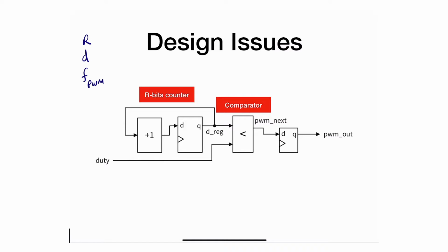So we need to improve this design a little bit so that we can control the frequency of the pulse width modulated signal. The solution for this particular problem is pretty straightforward. According to the synchronous design principle, everything should be connected to the system clock if you're designing synchronous circuits, so I should not be operating these with different clocks.